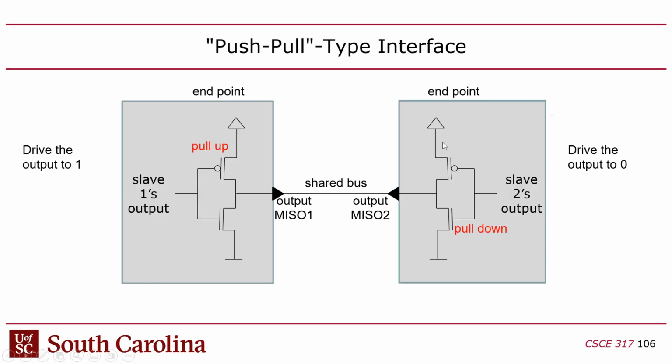Normally, when you have a driver or logic gate, at least in CMOS logic, every wire would be driven by a complementary arrangement of both types of transistors, where one is responsible for pulling the output, shorting the output, to high, to VDD, and the other is responsible for pulling it down to ground. For each individual transistor, I mentioned they don't really have an output.